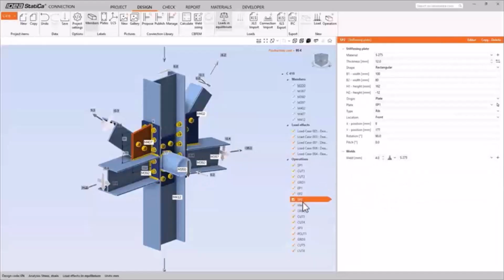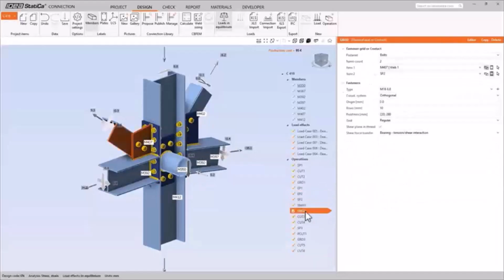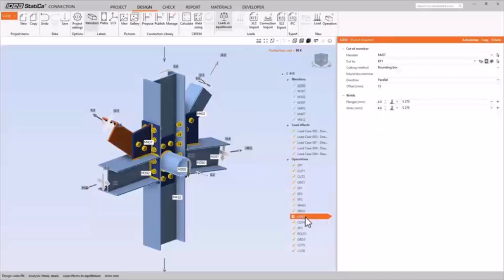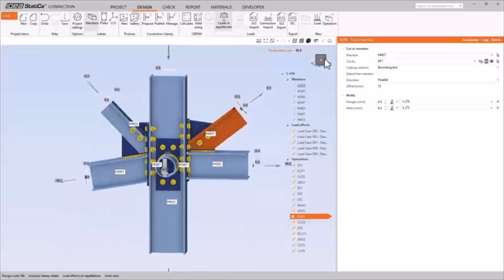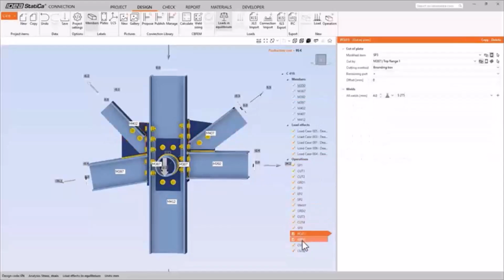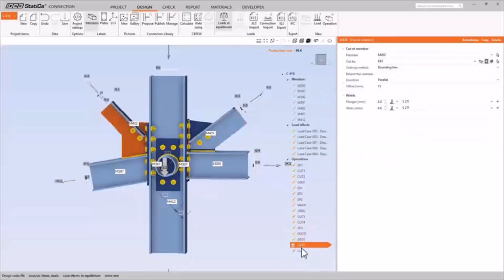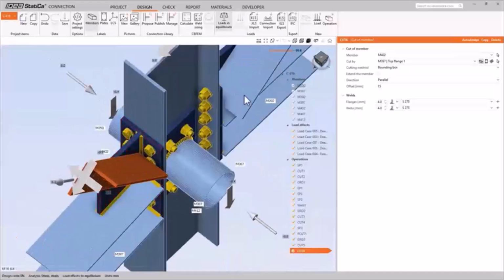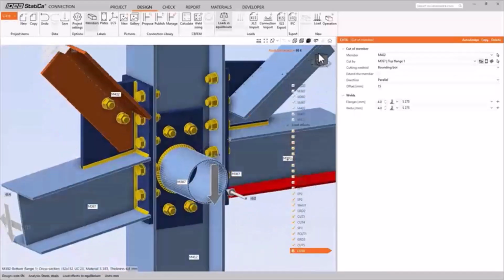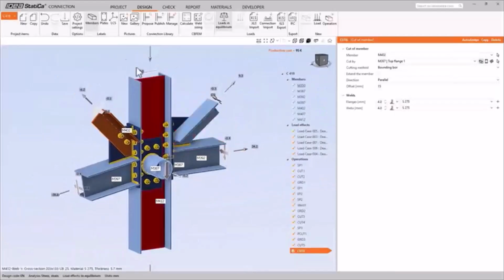So we have two end plates, two supplementary plates that are manually welded to the members, the bottom chords, and the braces that we've already offset by 30mm will connect to that gusset plate with an inline bolted connection, but the core, the braces themselves will need to be cut against several members, against two members each, in fact, and that is exactly what we've done there.